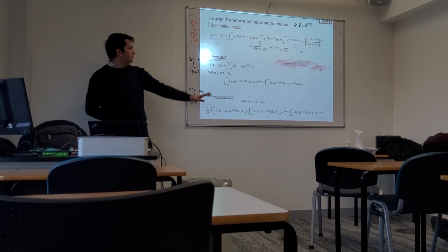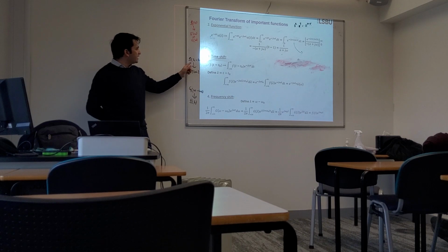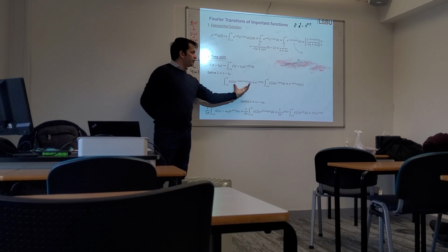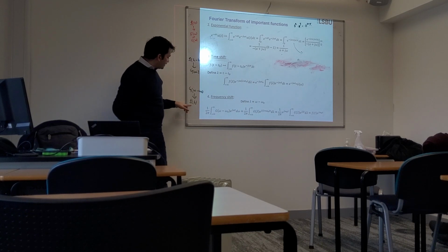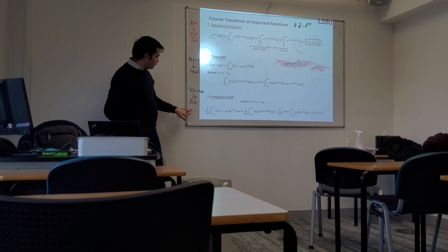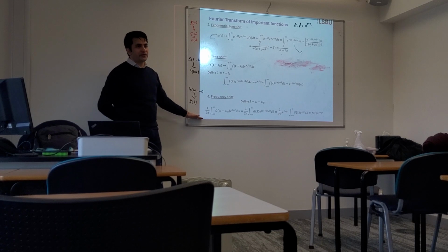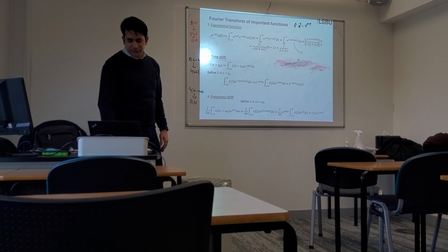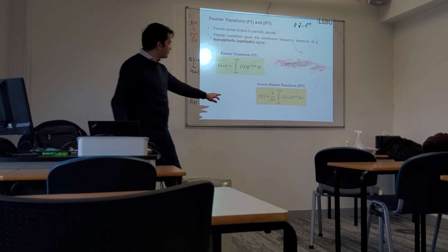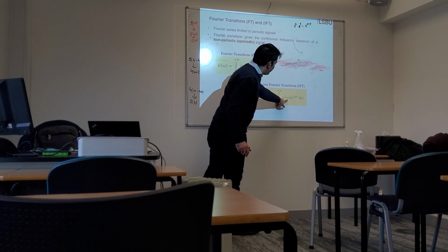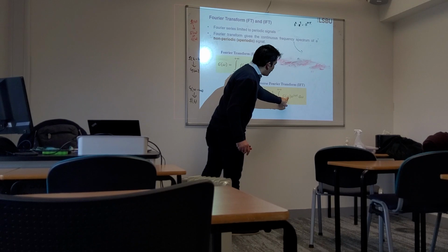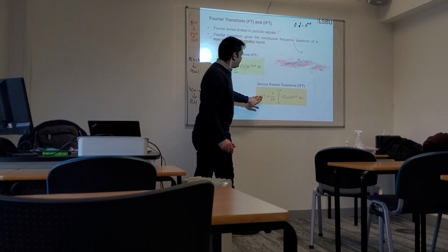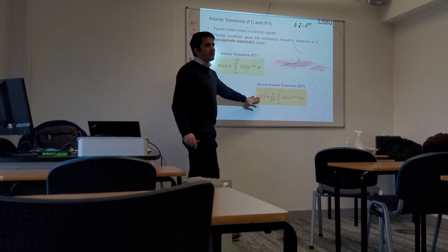It's the same as we have approached this one, but in this case, the function which was f of t, we used the Fourier transform. So here you can see that since you have g of omega and you want to find f of t, you will have to use the equation for the inverse Fourier transform. And you know the equation for the inverse Fourier transform is this one. So if we use this equation and somehow put the shift inside this, we can get to know what happens with f of t.